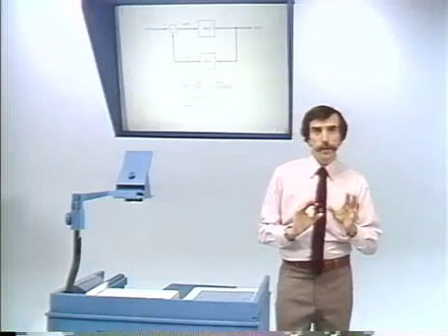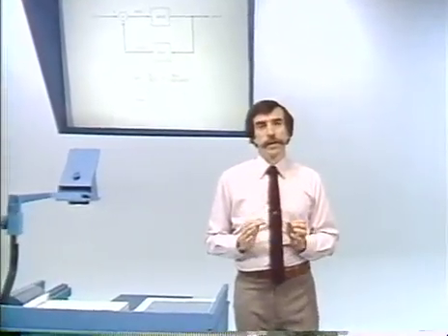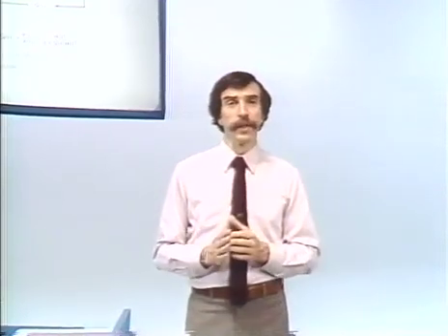Now, what I've just indicated is that feedback can be used to stabilize an unstable system. And as you can imagine, there's the other side of the coin. Namely, if you start with a stable system and put feedback around it, if you're not careful, what can happen, in fact, is that you can destabilize the system. So there's always the potential hazard, unless it's something you want to have happen, that feedback around what used to be a stable system now generates a system which is unstable. And there are lots of examples of that.